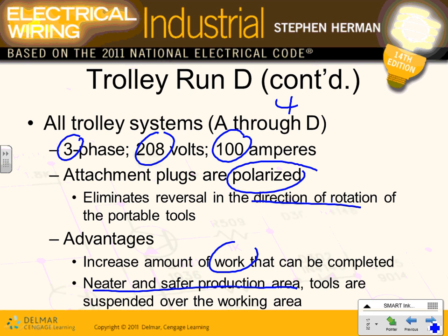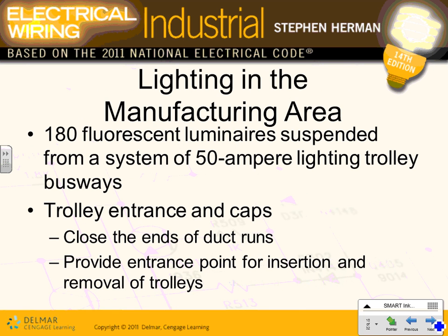Can I have a 600 amp panel and put all my receptacles in it? Yes. It's a bad idea. Voltage drop. Look at the voltage drop issues in that thing. And if something happened to this panel, you lost 600 amp worth of power in the whole building. What's the better option? The better option is to have 2 or 3 225 amp panels and separate them in different locations. So that's kind of chunking the load, guys. Putting chunks of the loads in different panels is good for maintenance, good for survivability of the system.